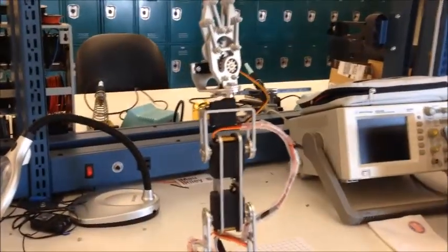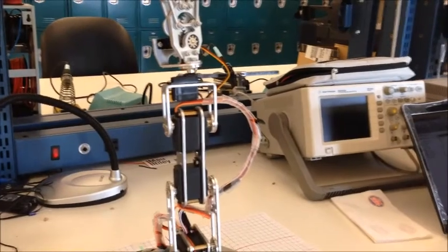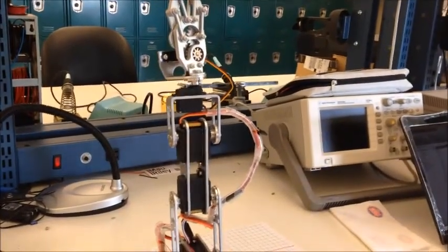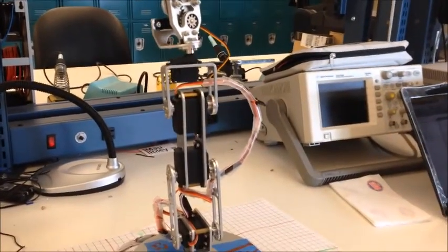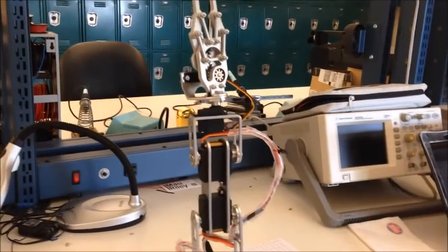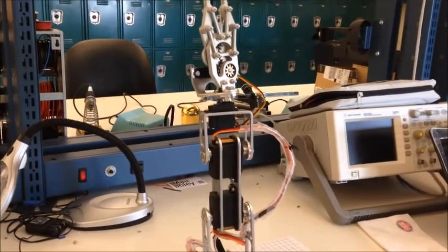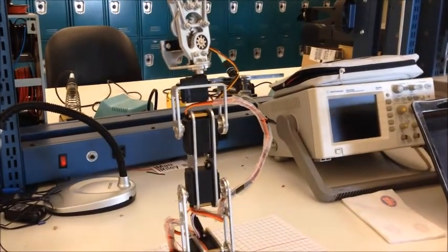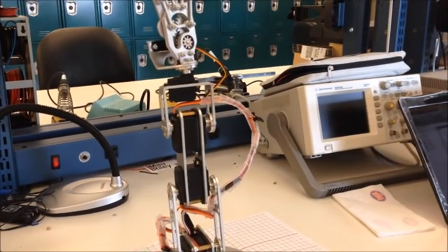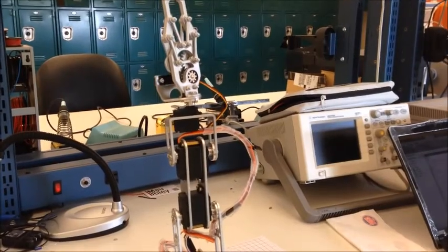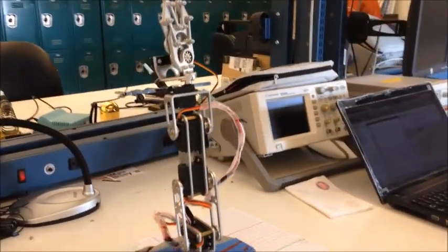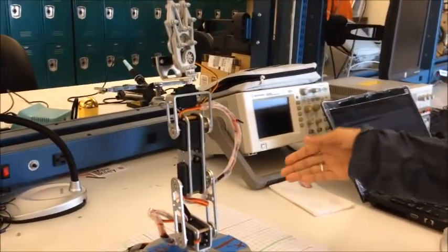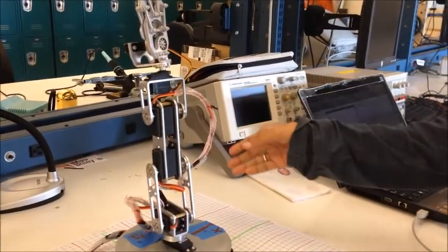So from this position, we've defined through the inverse kinematics 4 positions that we want to move to, and we're now going to move through all 4 positions. The first position is going to be X equal to 15 centimeters, Y equal to 26 centimeters, and Z equal to 3 centimeters. So it's basically the first quadrant at a height of 3 centimeters for picking up stuff.